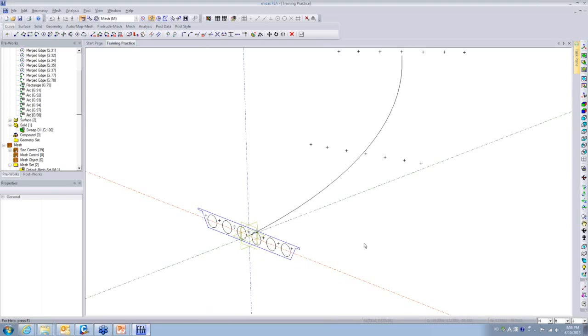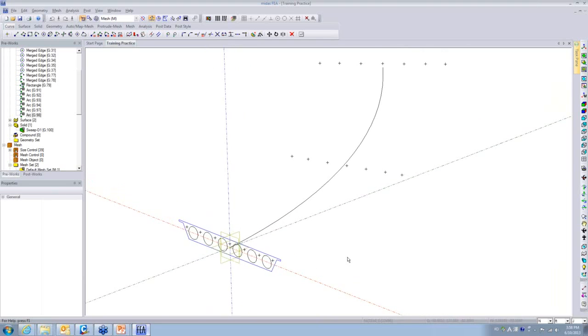Simply, you can generate the solid elements here, or if you want to model it with the plate, you can do it with the plate. But I recommend, if you want to do it with FEA, go with the more accurate result with solid, because the analysis time doesn't take much longer if you do plate or the solid in this simple model. So I can generate it for you.